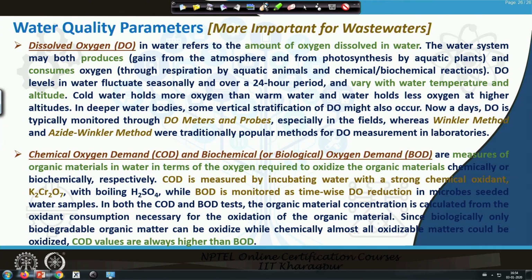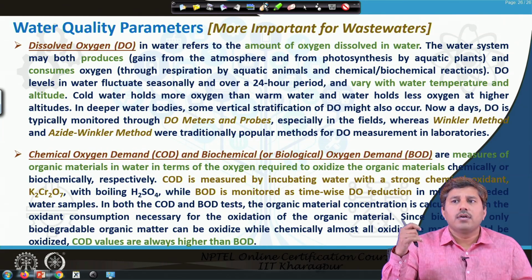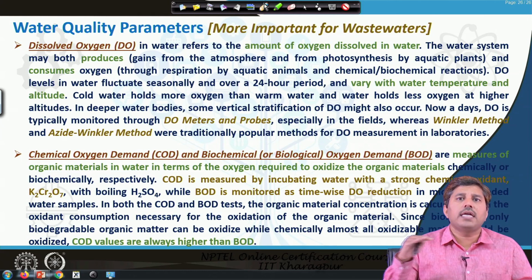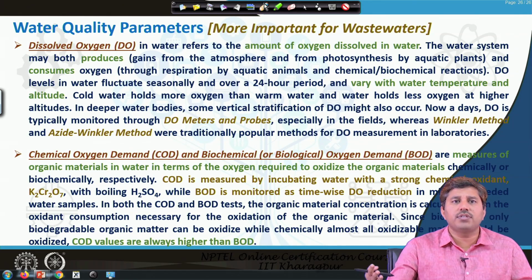So, if a water sample contains organic carbon, we may seed it with microorganisms. In the process of decomposition of organic carbon, the DO level will reduce. So, we measure the initial DO level and the level after certain times. Generally, BOD is measured after 5 days. So, after 5 days, how much the oxygen level has reduced, we report that as BOD 5.